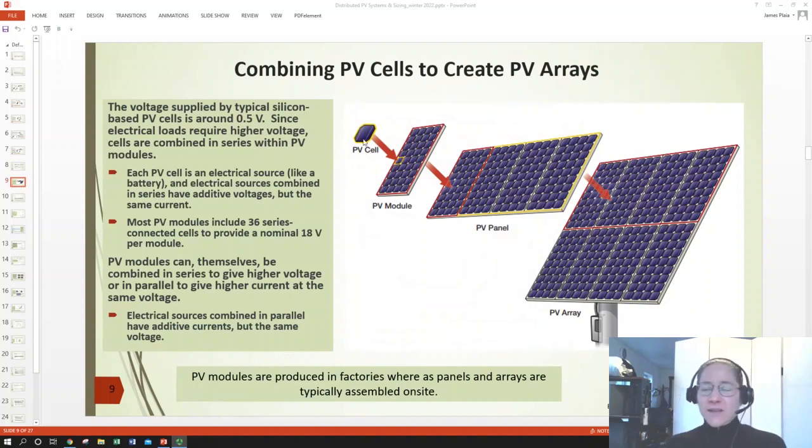So how do we go from a solar cell to an array? Well, one piece at a time, basically. Solar cells are manufactured from some kind of photoelectric material, usually doped silicon, although it can be made of many different types of materials. Some of the new architectural materials take advantage of electrochemical interfaces with dyes that are photosensitive and can produce the same effect. Lots of different advantages in applications: weight, flexibility, etc.